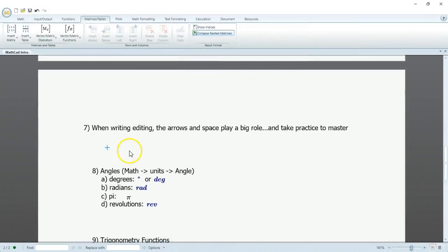I just want to mention that it does take some practice to become familiar with how Mathcad handles its parentheses and fractions and divisions and exponents and so on and so forth. Let's say we had a simple equation where we had a rectangular beam with a base of 4 inches and a height of 10 inches, just a cross section, and a vertical shear force acting on it of 500 kip. We have a distance from our centroid. We'll say we want to investigate at 3 inches.